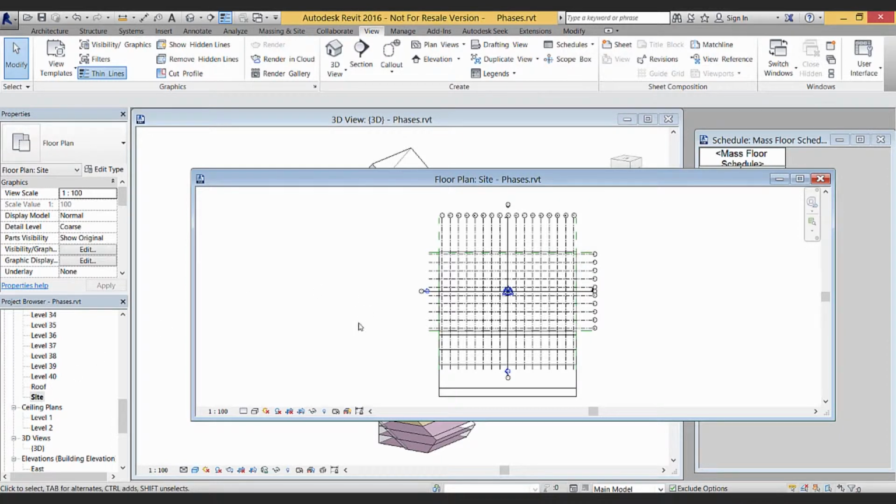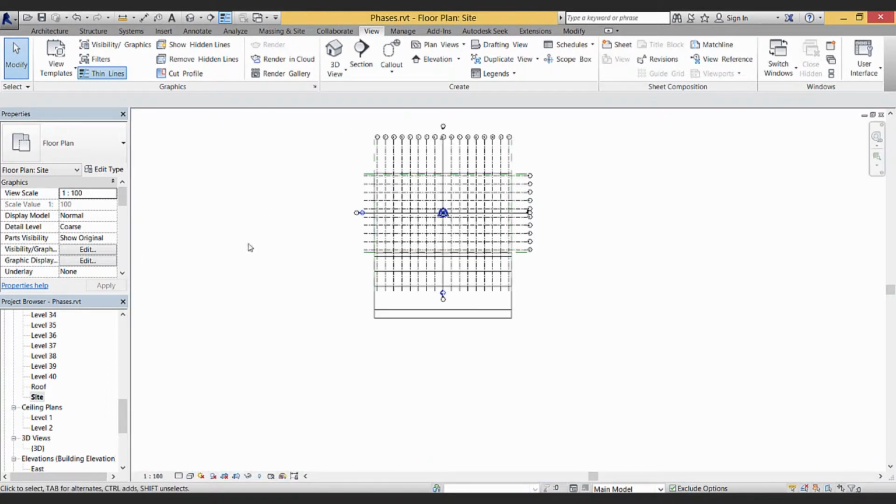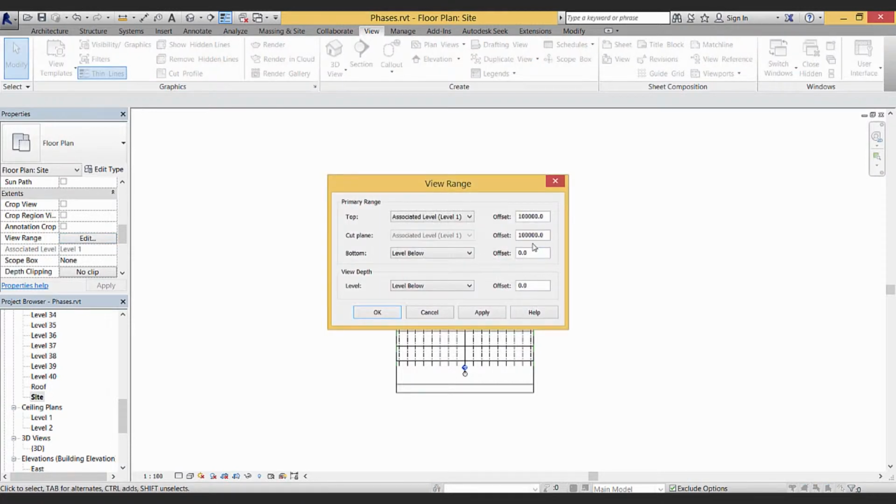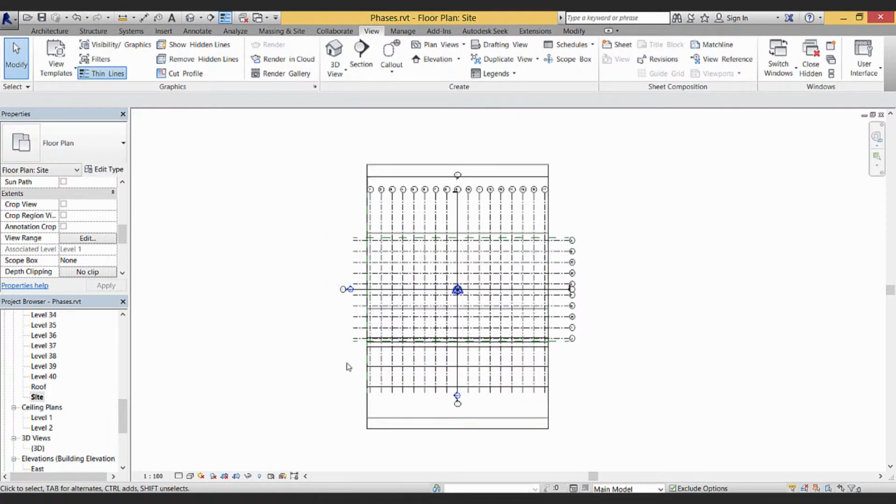The site view is basically a plan view inside Revit that has a very high view range. You can check out the view range of any view. That's basically where in the model this view is cutting the model. This is a parameter in any plan view. You can go down to the parameter group Extents and check out the view range. For any site view, this is normally going to be a pretty high number. So basically you're cutting the model 300 meters above ground and looking down at it. This is a pretty good way to have a plan view looking at everything, basically.